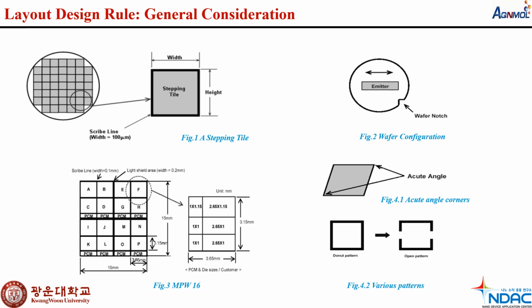And finally, GDSII stream file format and standard cell. When the layout database is submitted, it should be in GDSII file format. These files are also used to unify the entire set of chips on the wafer, and additionally it encloses a pattern, which is shown in figure number 4. The pattern is applied on the metal layers.